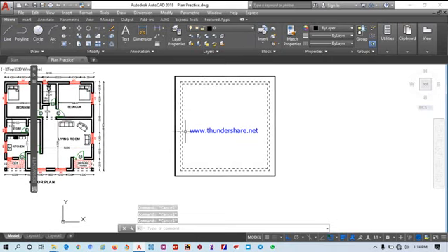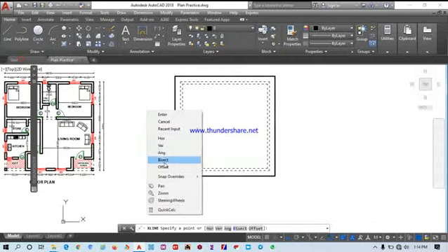So the next thing to do right now is to bisect the angle of this roof, making use of our construction line. It bisects our ridge. Ridge is the topmost part of the roof, or where the two sides of the roof meet each other. That's our ridge. So let's go to draw construction line. So right click, it will bisect it by angle 45. That's the norm. Bisect by angle 45.